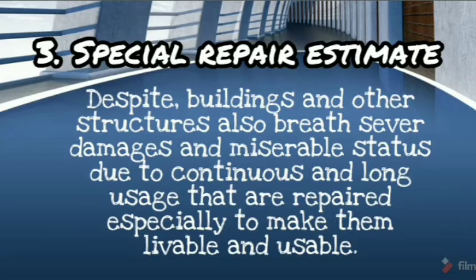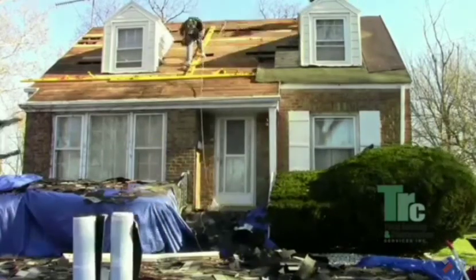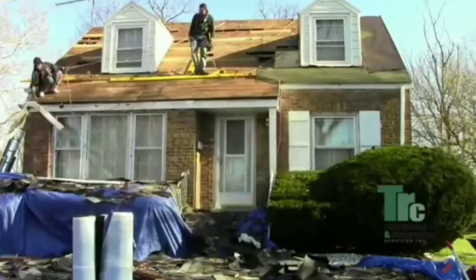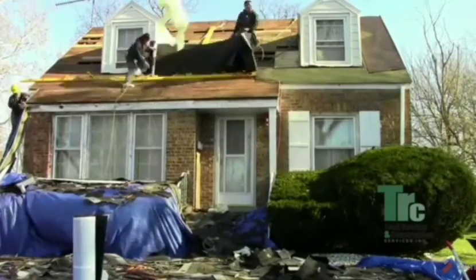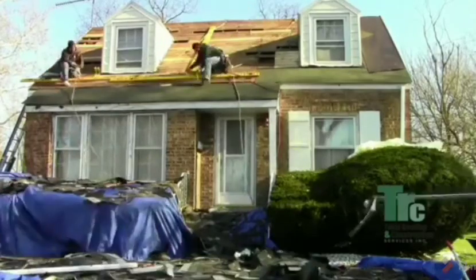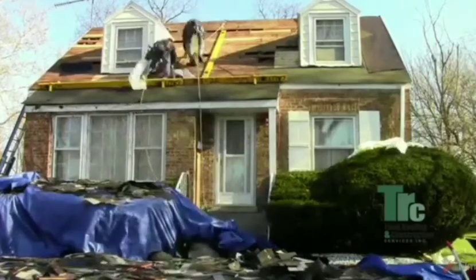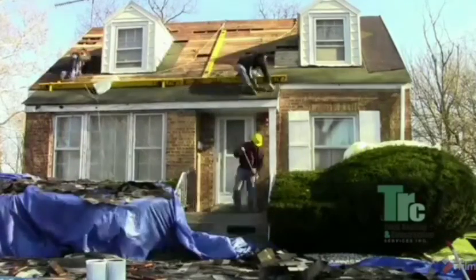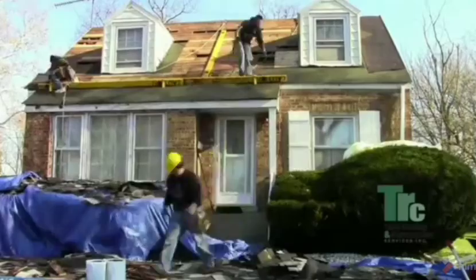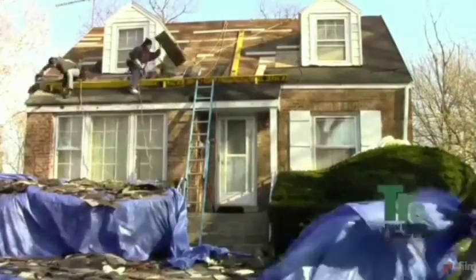The special repair will include removing of spoiled floor or roof and constructing a new one, removing broken doors and windows and wood crafting a new one, removing the spoiled plaster and plastering new ones, etc. Road special repair will include filling up patches showed up in the surface of the road, ensuring rigidness of the road banks and footpath maintenance, etc.